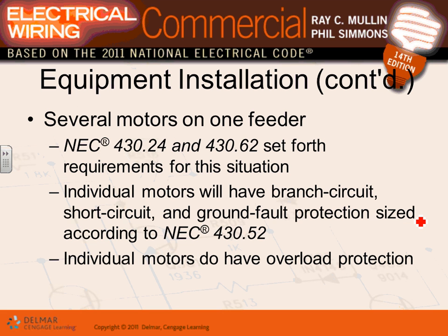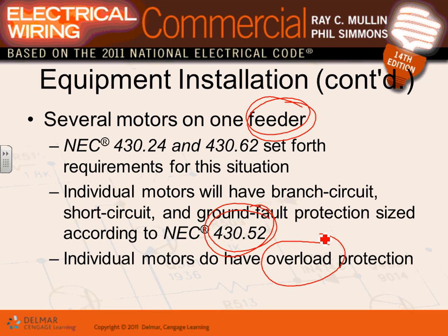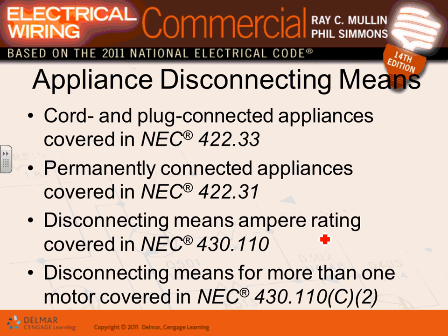If you have a feeder, now this is not a branch circuit, a feeder, it's the same way, guys. We take 125% times the largest motor plus the full load current of all the other motors. And when we size the overcurrent protection device, you guys remember, we take the largest overcurrent protection device of the system plus the full load current of all the other motors, and we go down on the overcurrent device. In a case like this, you can have, of course, overload protection for each and every one of these motors, as well as short circuit protection.